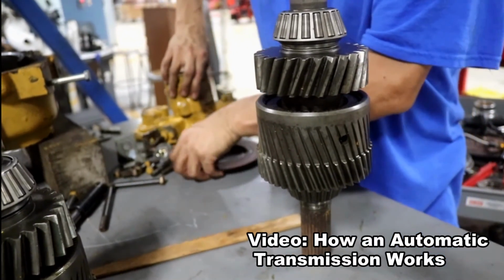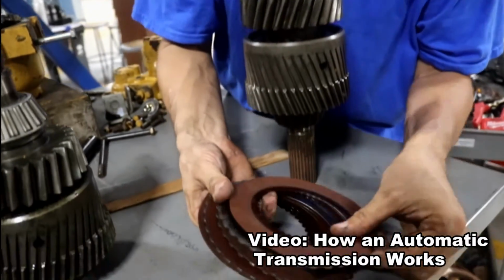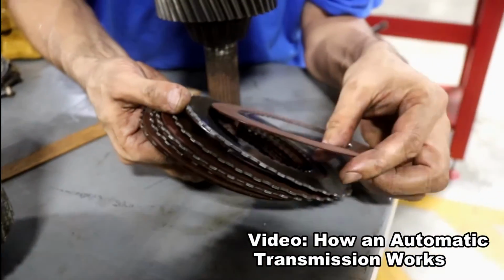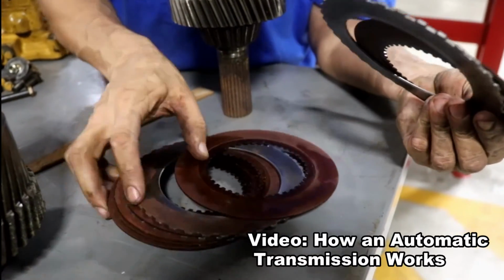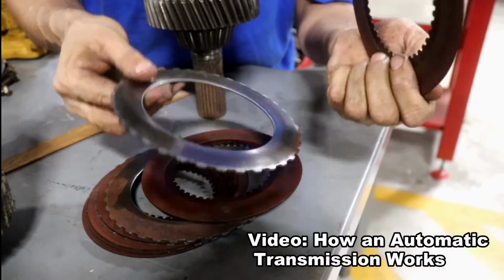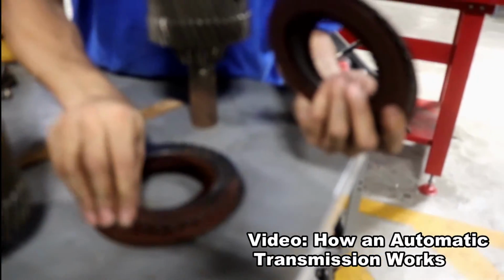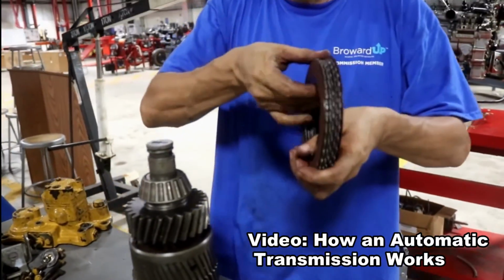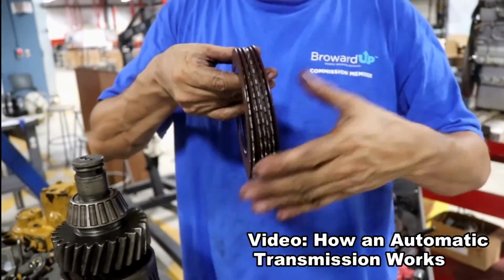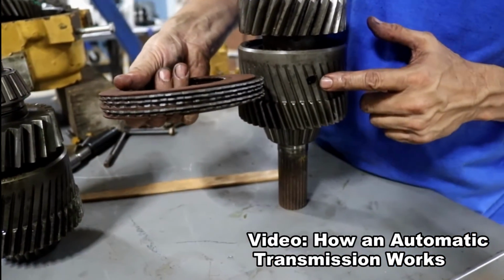In the clutch pack, I have a set of friction discs separated by stainless steel plates: friction plate, stainless steel plate, friction plate, stainless steel plate. I have like 15 and 15, or 20 and 20, depending on the clutch pack. Those elements are located internally here.